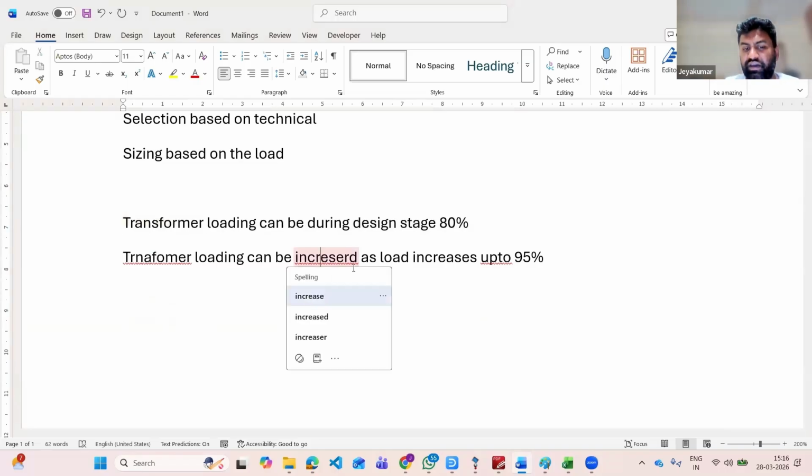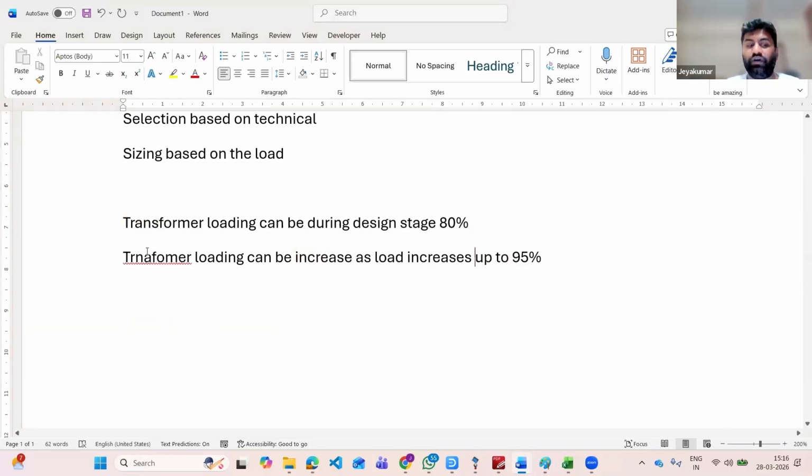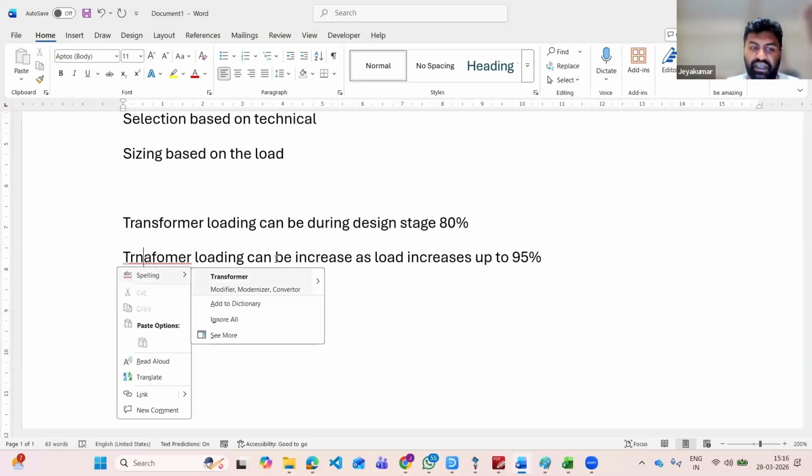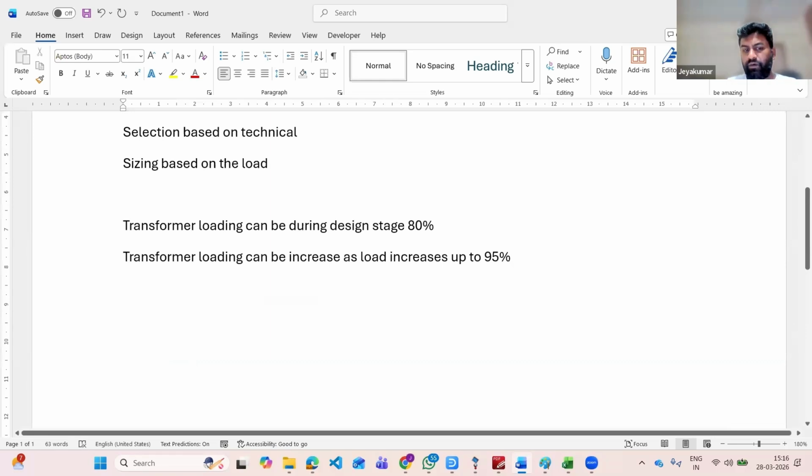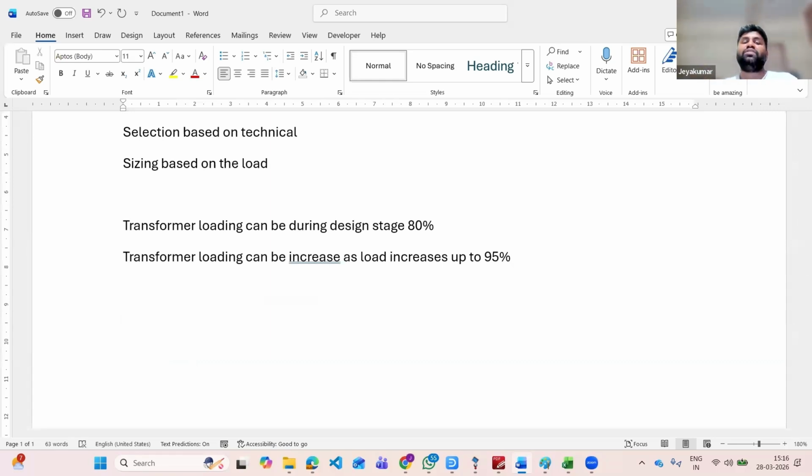So you don't ask me what is the rule. Basically it's a design good practice. Some companies will have this as a rule, or kind of an internal standard. Okay, because they know that practically some sudden loads may come up because of internal workout, or another department will give some load, and various reasons. So they have some practical consideration like that. Okay, but technically up to 95% you can load, guys, actually, right?